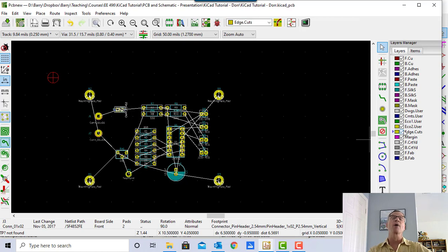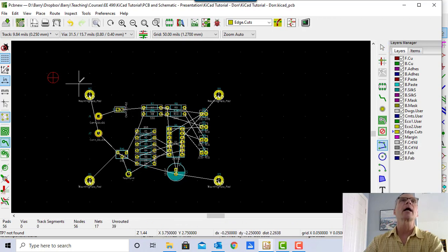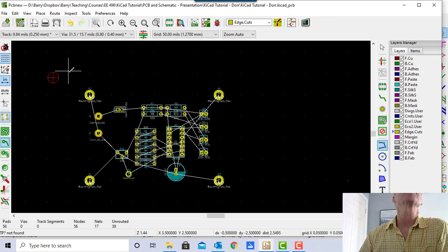And what I'm going to do is first select it. That means that that's my working layer of the board. Layer isn't really a physical layer. It's just a bunch of information. So what's going to happen here is I'm going to draw lines, and these lines are going to end up being the outline of my PC board. So now I'm going to say Add Graphic Lines. I'm going to pick this tool, and I'm going to use my grid, and I'm going to make my board a little big. So I'll go right over to here.